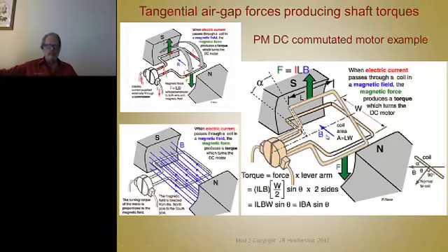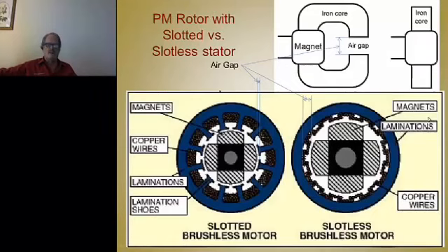But the other thing is, with this big a gap, this B field here is going to be awful weak, so there's got to be something else here. There's got to be some iron inside of that, and if you create a big force, 100 Newton meters or something like that on a wire, well, it's going to bend. You've got to have something to support it. So this is good for the mathematics, I guess, but it's not good enough for me for a conceptual visualization of what's going on inside the motor. So I'm going to kind of twist that around a bit and think of it in terms of a concept here that maybe we can better get our arms around.